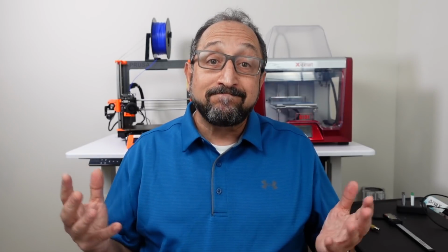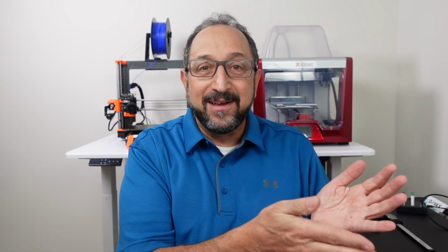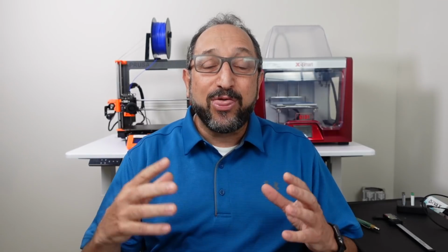So, what did we learn? Depends on the print, depends on the printer. Both produced pretty good prints on both printers. Interestingly enough, there were variations. So the Cura Slicer actually produced better fine type with default settings on the Prusa than the PrusaSlicer. But the PrusaSlicer produced better fine type on the Quiddy than the Cura Slicer. So it depends on your printer and your slicer. The bottom line, you need to tune your printer and your slicer and your filament to work together. 3D printing is as much art as engineering.